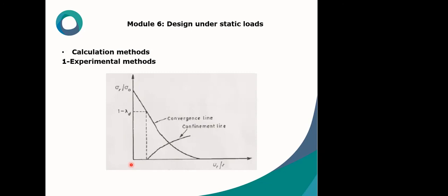Following the convergence of the tunnel section provides the possibility of controlling the appropriateness of retaining and forecasting the required reinforcement if necessary. From my point of view, this concept should be understood perfectly before we can go further, if we would like to have deep insight of a tunnel behavior in different conditions. Even if we are going to design a tunnel by numerical simulations, the convergence confinement concept is used during the process.